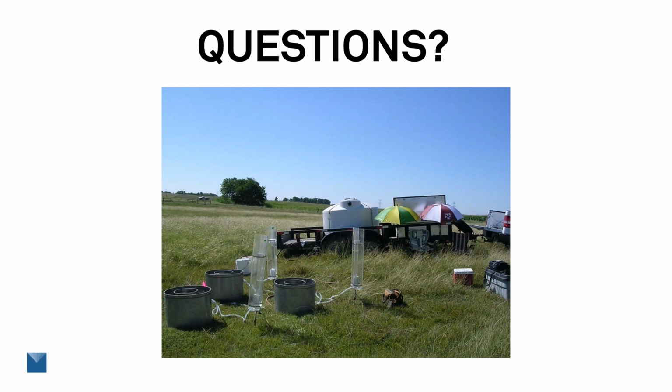Yeah, I think to a point that's possible. For example, what we're doing with the HYPROP is we're taking two measurements of water potential and measuring that gradient, or even with the flow cells, we're using that water potential measurement again. And we have essentially a known water content and known changes in water potential. I think it's possible to do it with the lysimeters, but you would need to really have a good understanding of the actual water flux coming in.